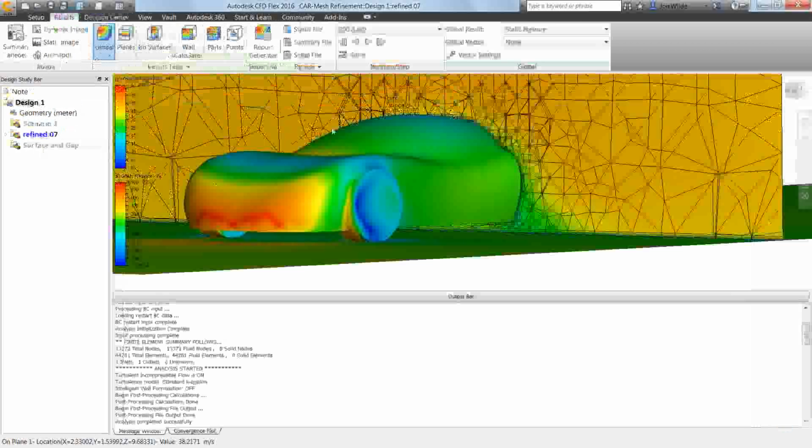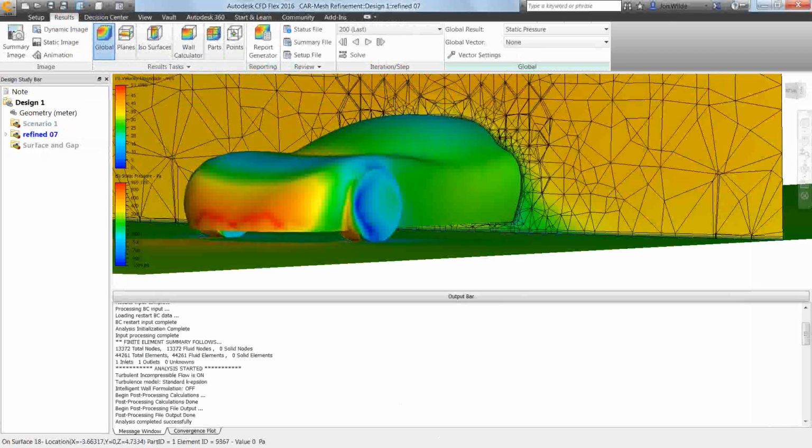Yeah, I got a question here that I'm not sure if I understand. We'll see if you grasp it. Is there any provision by doing mesh adaptation by defining a region? You might want to frame the question a little better if you've got time. But I guess what that means is, can you use meshing regions up front and then adapt the mesh from there? And yeah, you can, right? You can use meshing regions and any technique you want to achieve that initial mesh. And that will be treated as the mesh that CFD then moves forward with as it adapts. It's a good question, I think.